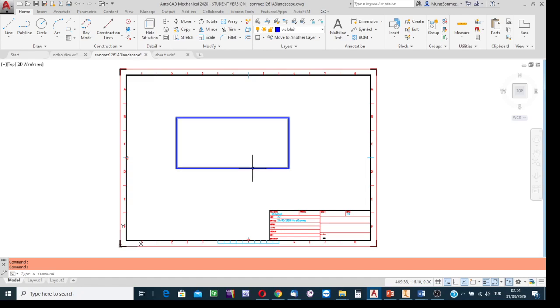In this example, say that for a certain portion of the bottom side surface, there is a requirement to satisfy. The requirement is not to be satisfied for the entire surface. Only for a certain portion of the surface do we have a requirement to satisfy. So we need to use a chain line.